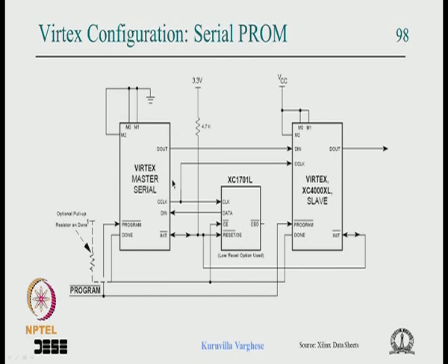So not only that, while prototyping the FPGA can be programmed through JTAG, this SPI PROM, not this PROM, the SPI type PROM can be programmed through the JTAG port, which often when you buy an FPGA board these options will be available.